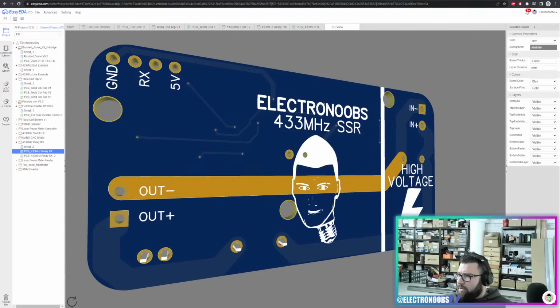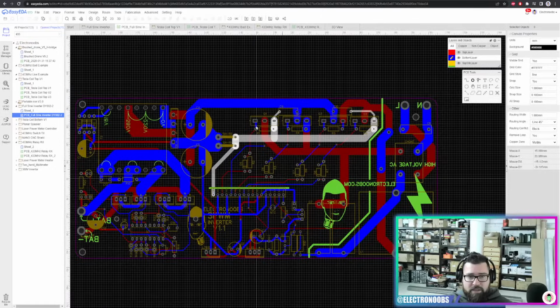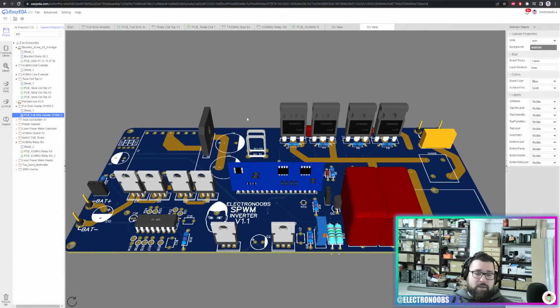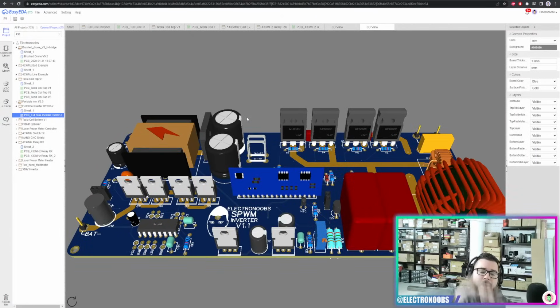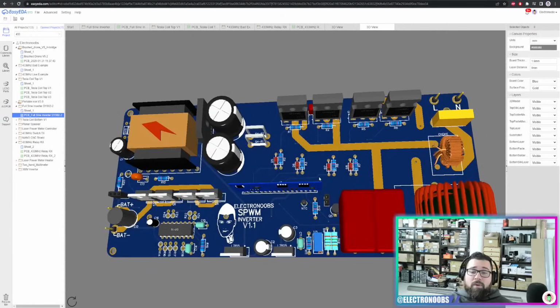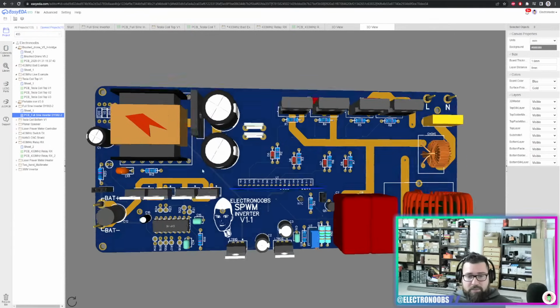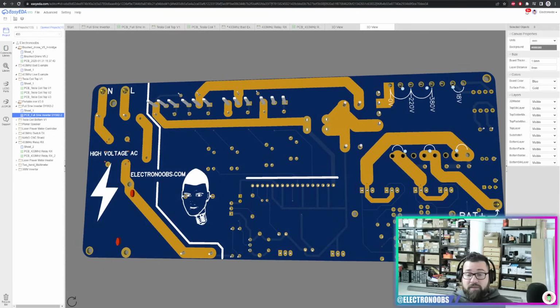I have a video with my new project, because this PCB here, if we open it in 3D, you can see it here. This is the PCB. As you can see, it has a lot of components, and this will use 500 watts. So we need a lot of power to go through these tracks. So instead of just ordering a PCB that is very, very expensive with a lot of copper, just expose the tracks like this one and just fill them with copper, with solder, I meant.